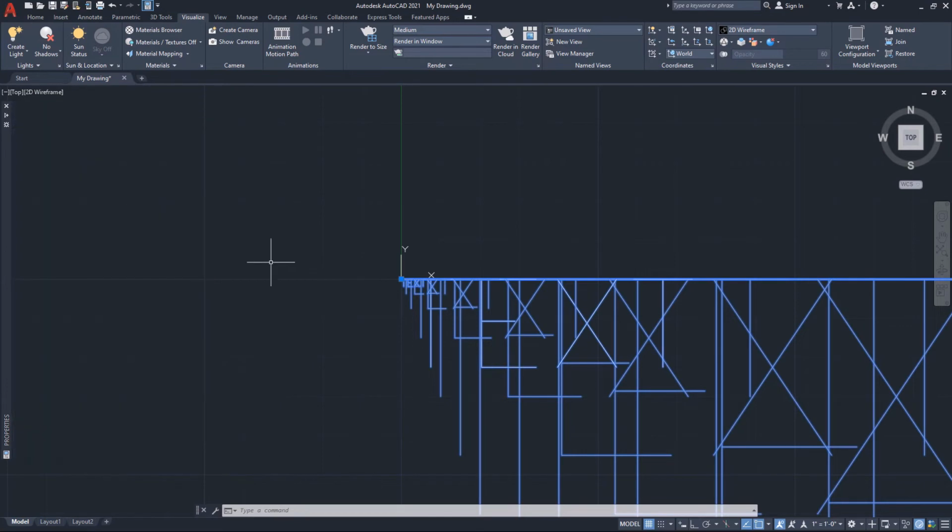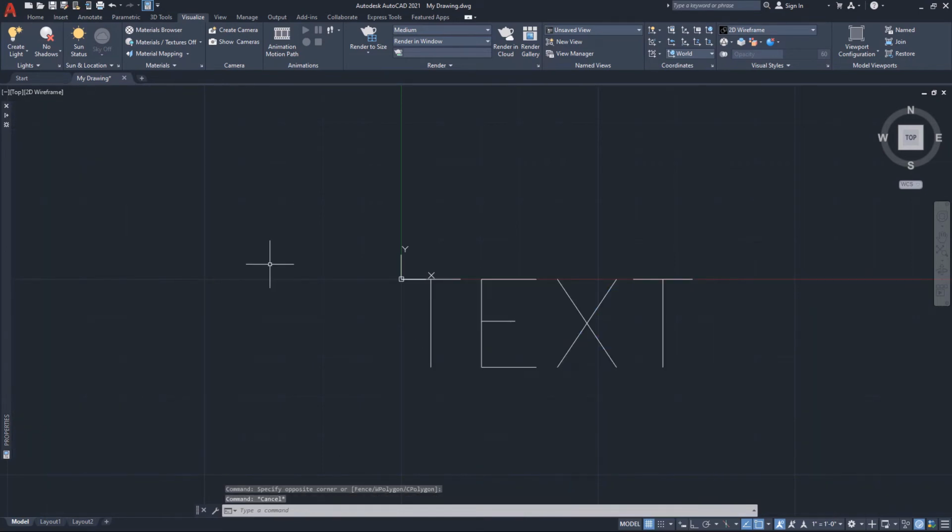This is an example of how annotative scaling is adjusting the font height in model space so that it remains legible in model space for the user, while in a viewport window on a layout tab, which we will investigate shortly, will display at the 3/32 of an inch height assigned to this text.